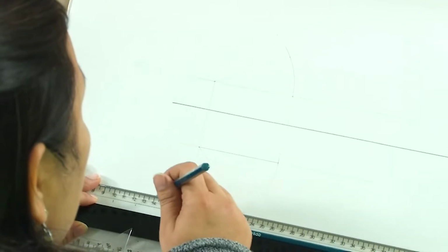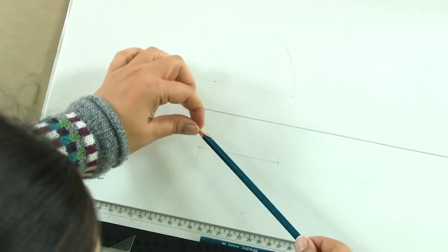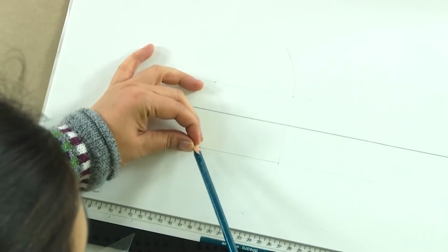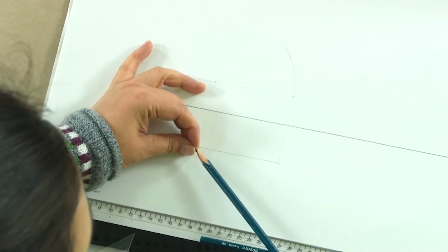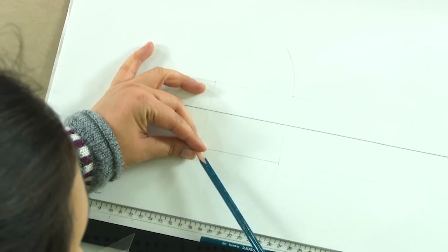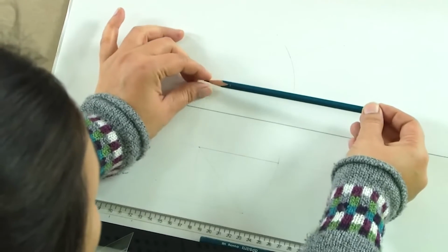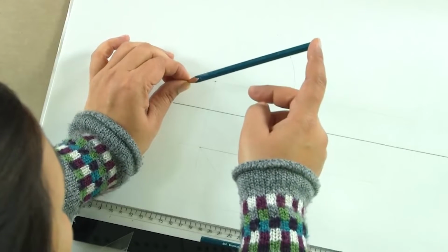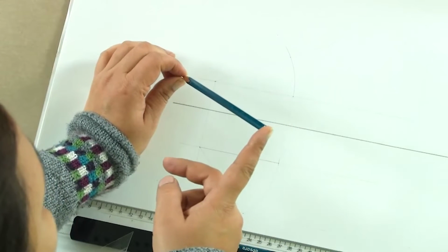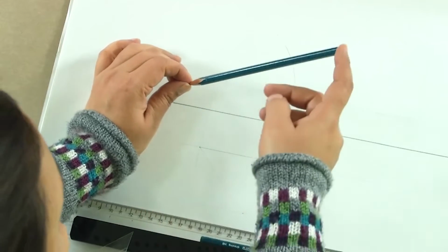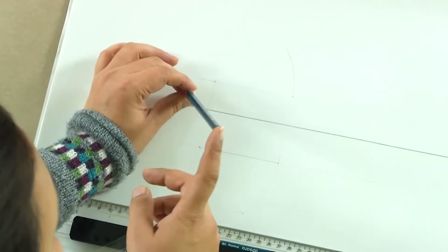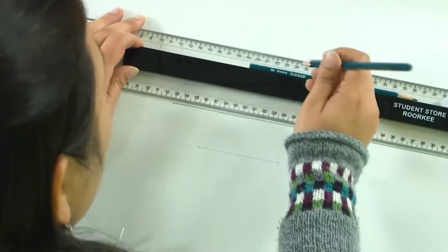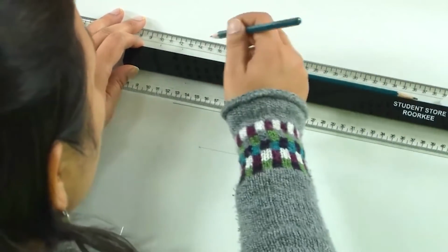Now, if you remember, when I was explaining to you the movement of the line, we said that if it is inclined to one plane and it is inclined to the other plane as well, this is how, in a conical manner, the line will move. And similarly, if it was inclined to say HP at an angle of 30 degrees, to make it at an angle of say 45 degrees with VP, we will have to incline it in a conical manner such that the top point maintains its distance from the horizontal plane and the vertical plane.